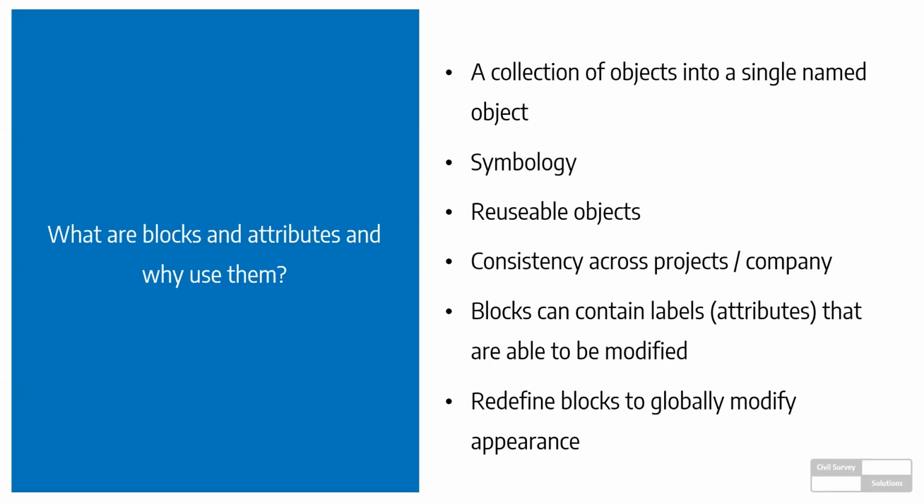When you copy that block around, you're only creating a single instance of that block reference through your drawing. You're not duplicating those 10 objects multiple times. So I'll show you the significance of file size when we come to creating a block and not creating a block a little further into the session. Blocks are ideal for symbology.